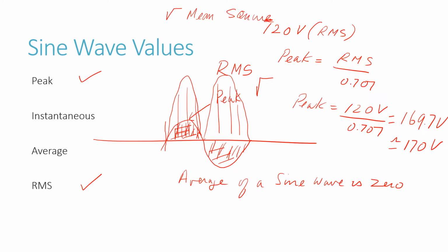Working backwards, you square first, then you take the mean, and then you take the square root. So you see you get the root mean squared. So that's where root mean squared comes from. RMS. It's the root of the mean of the squared values. And that is done so that you can get a meaningful value. Because if you took the average value, you would get 0.